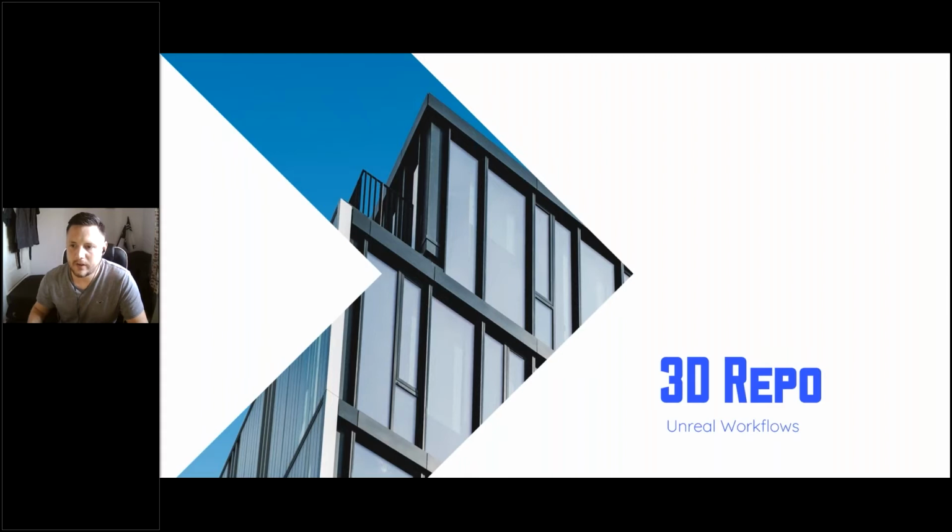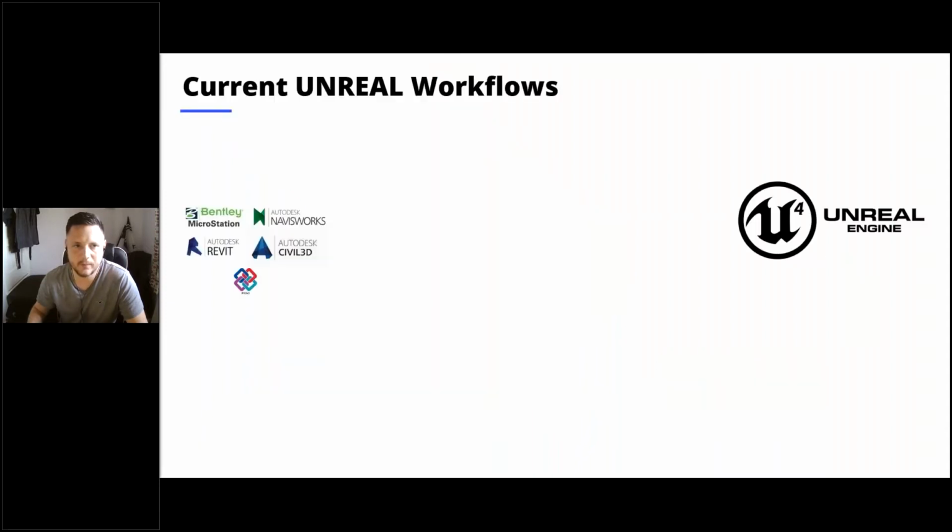So now I want to have a look at some of the Unreal workflows that we're currently looking at, and that we hear that our clients are currently doing. So what we're talking about here with Unreal workflows is how we go from BIM data to viewing it in the Unreal Engine or a published application. So the first and most obvious one that we hear about is exporting FBX files and re-importing them.